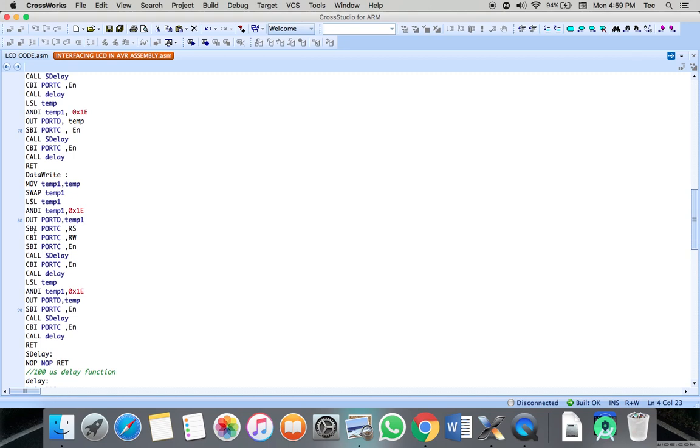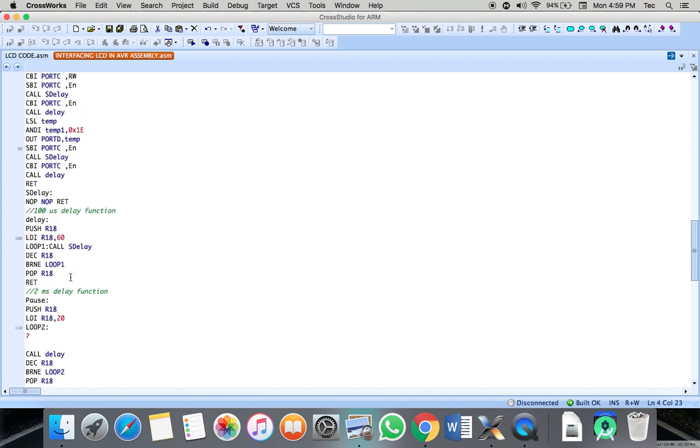Then again you set the bit for port C for reset, then again you clear the bit for port C to write. Then again you set the bit in port C, enable, just like that until you call the delay. So this will keep repeating. So now we come to the delay.